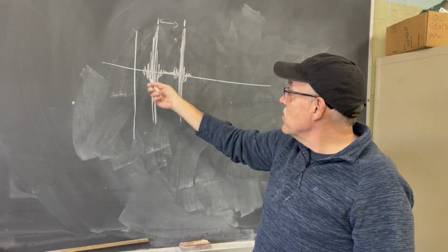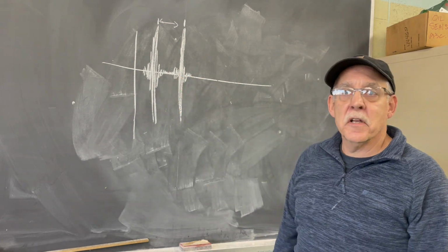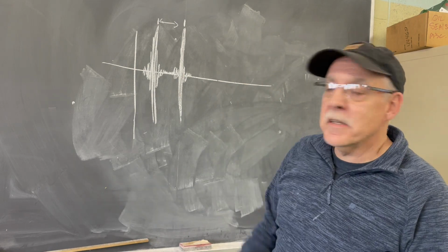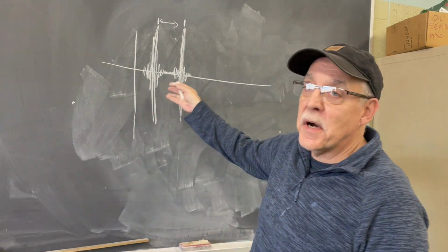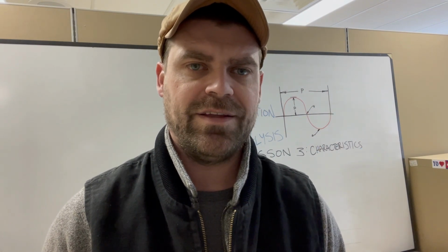And so as soon as I see a waveform like that, and I'm looking at a gear, I know that I have a broken gear tooth. I don't have to do any other measurement. I don't have to do anything. I can just tell by the pattern that it shows. So that complex vibration pattern, also known as the time waveform, can tell us a lot.